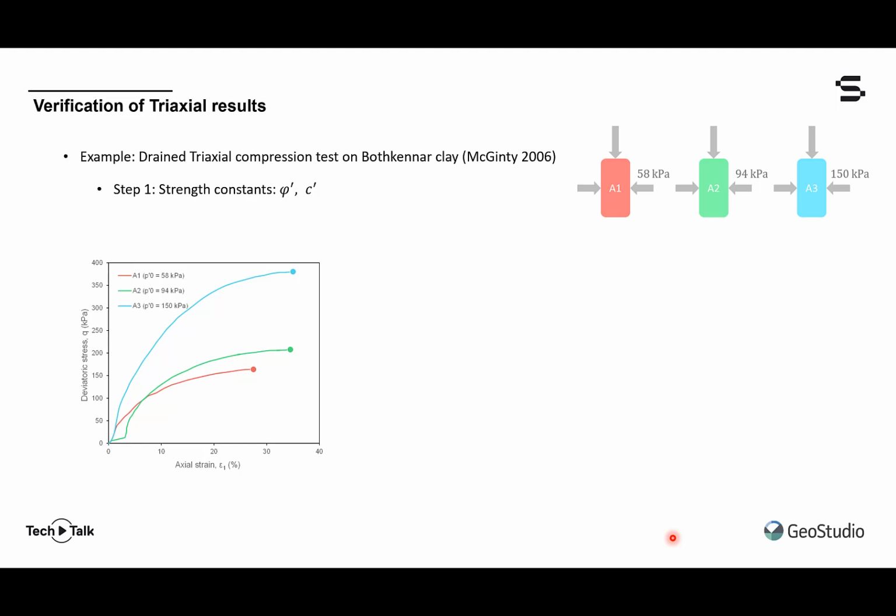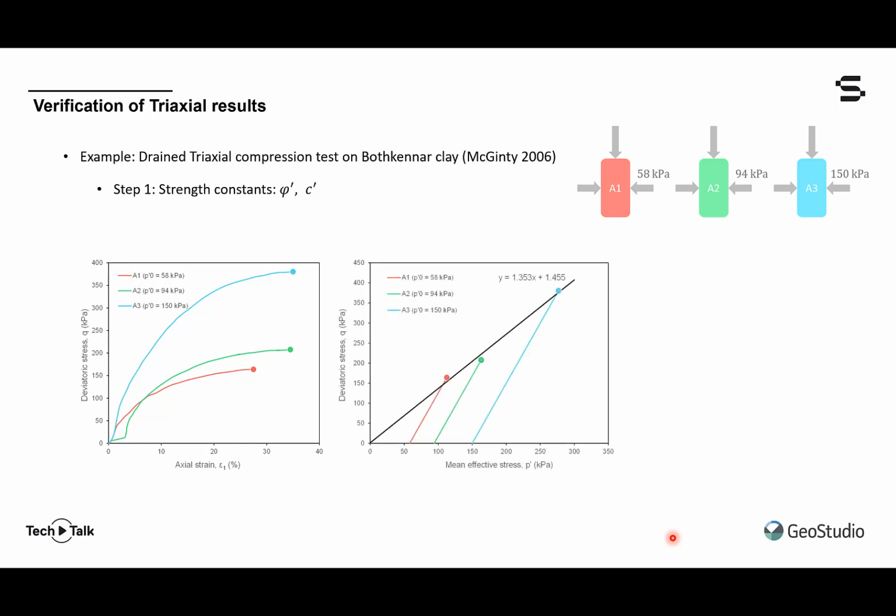The deviatoric compression stresses in these triaxial tests continued until failure was achieved. The failure state of each test can be represented as a single point in q-p space. And then a failure line can be passed through these points, and the slope and intercept can be determined using a trend line or the least squares formulas presented earlier.